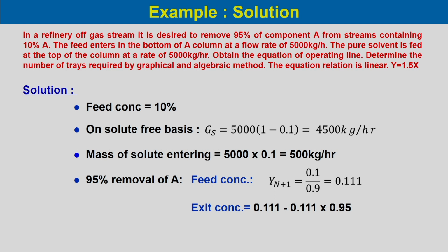Now, the exit concentration is 0.111, the inlet, minus 0.111 into 0.95, because we have to remove 95%. So, the exit concentration comes to around 0.006.